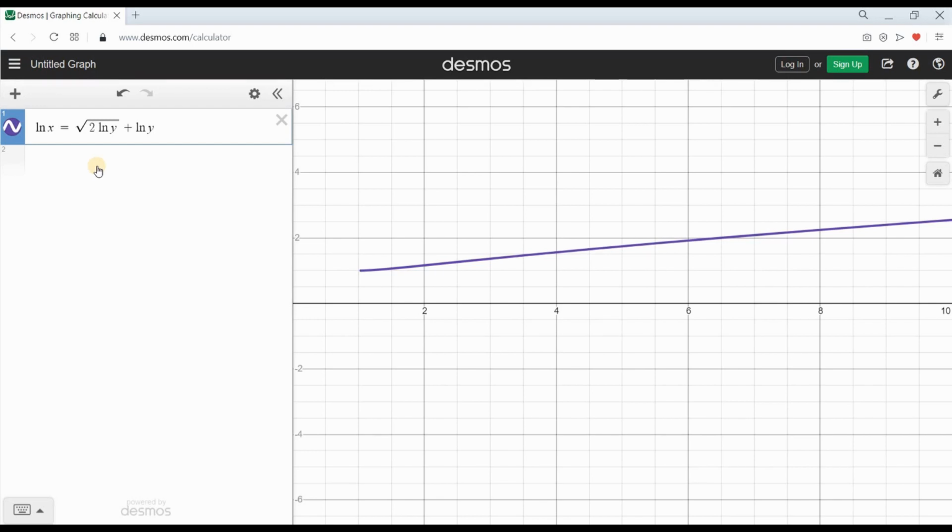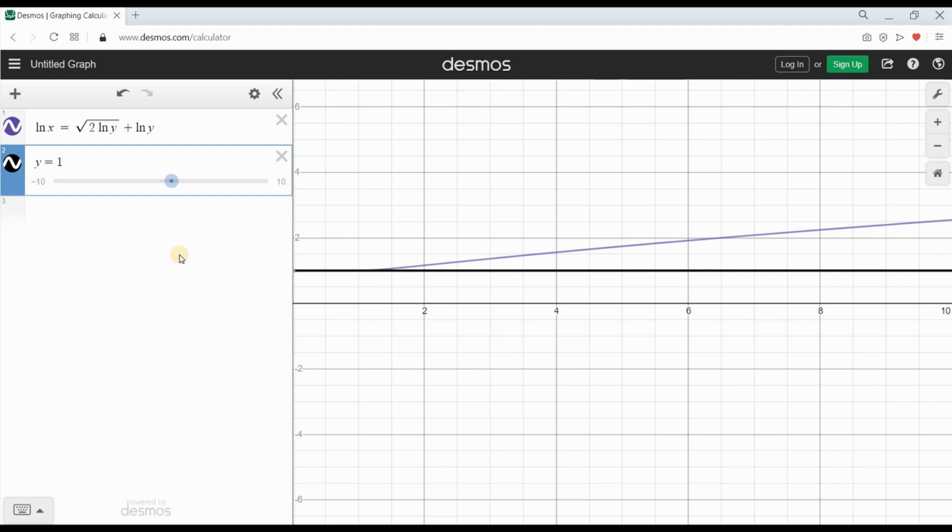So we're tasked to draw the streamlines that go through this point 1, 1 at different times, namely 0, 1, and 2 seconds. So for 0 seconds, the equation becomes y is equal to 1. Looking at the equation for the streamlines, y is equal to c times x to the power of t over 1 plus t. If the streamline wants to go through point 1, 1, c has to be 1, right? The constant is 1. So with that in mind, for t equal to 0, the streamline reduces to y is equal to 1. That is the black line here.